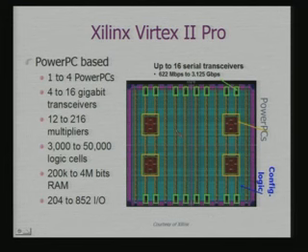This is an example of the kind of programmable platform that I was talking about, the Xilinx Virtex-II Pro. It has four PowerPC processor cores sitting on the same SoC along with the FPGA logic to add on hardware, and it has serial transceivers to transfer the data.